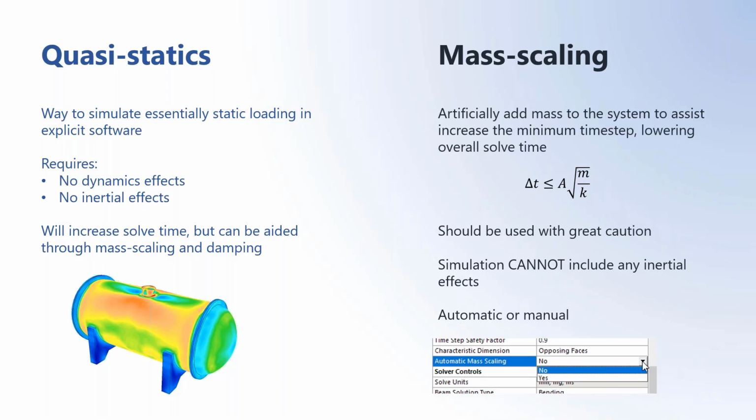Now, depending on who you ask, this isn't a great approach necessarily for quasi-statics because you can get really massive energy errors that way. If you think about the equation for kinetic energy, it's something like 1/2 mv squared. So if you double the mass of your materials, you're doubling the kinetic energy. And because energy is the way that explicit dynamics really tracks error in your simulation, you can introduce a lot of error that way. So this isn't necessarily the most sound method for simulating quasi-statics.